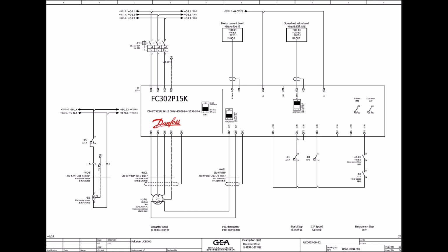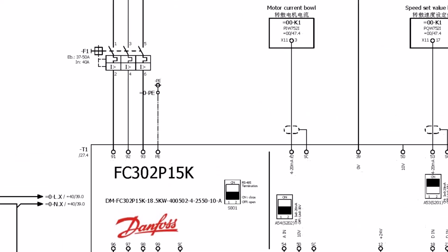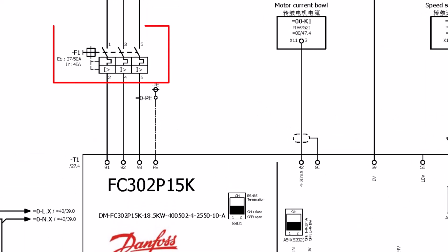Let's move to the other components in the drawing and go through them as examples, just as we did previously. Here we're taking the breaker as an example to read from the drawing and locate it in the panel. The breaker could be tagged as Q1, F1, or another designation, as different countries have different standards. In this drawing, it's labeled as F1.